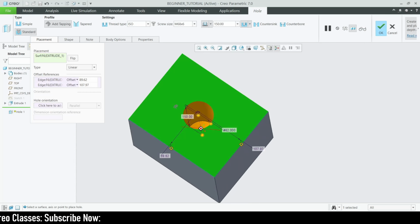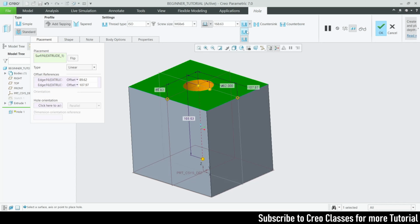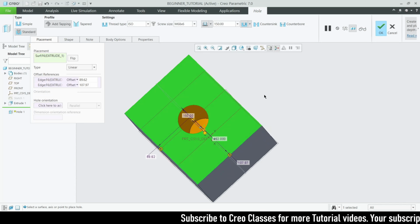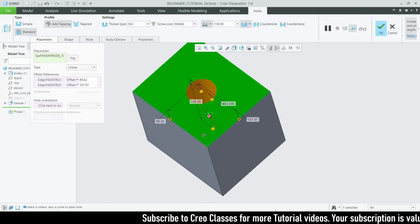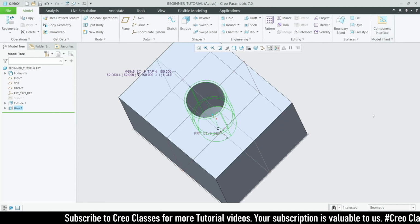Okay, so this will be the depth of the thread, and you can also select whether it's a countersink or counterbore. Okay, so I don't want it, so I'm just unclicking it. Like you can also use this option for countersink and counterbore. So now, that's all. We have created this whole feature, and you can directly click on OK.